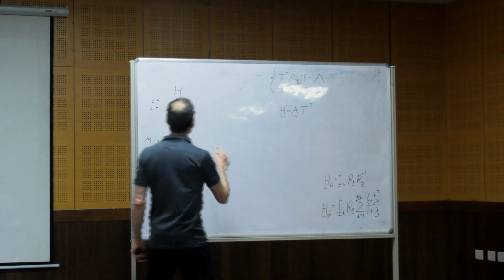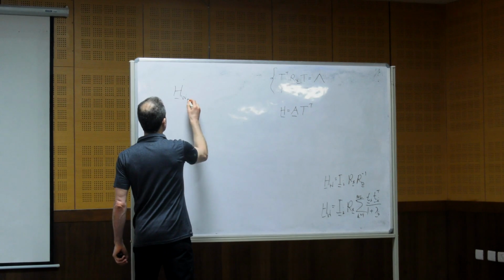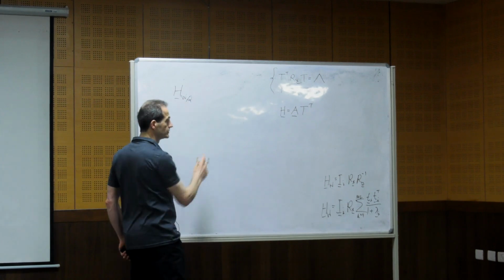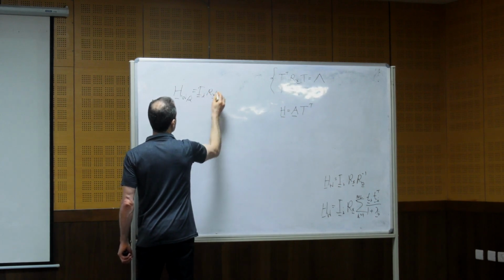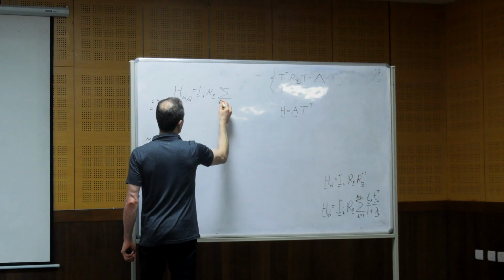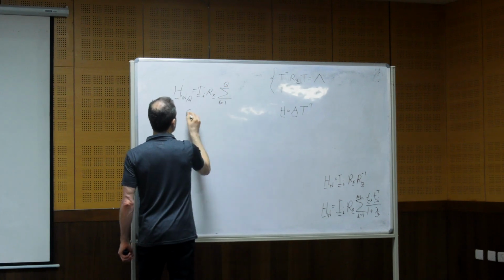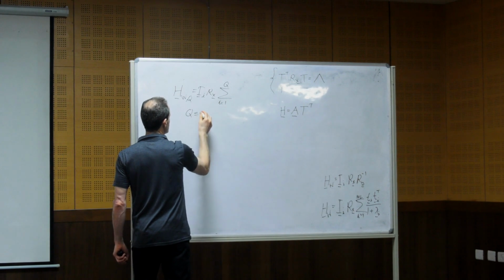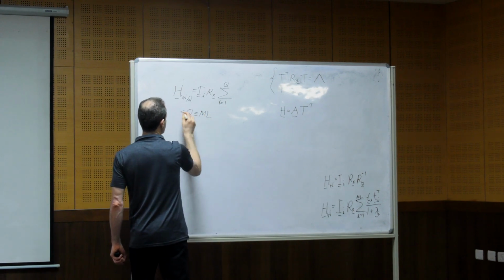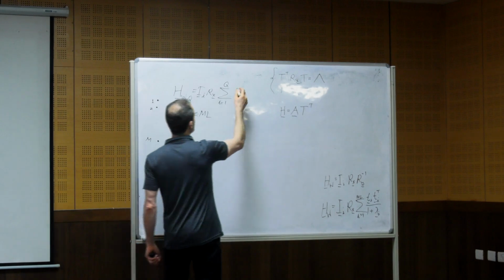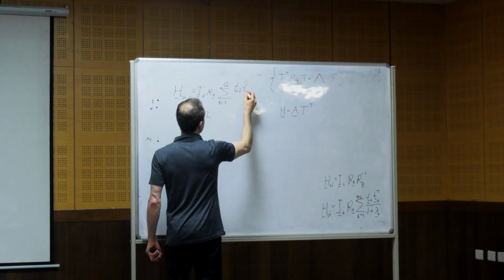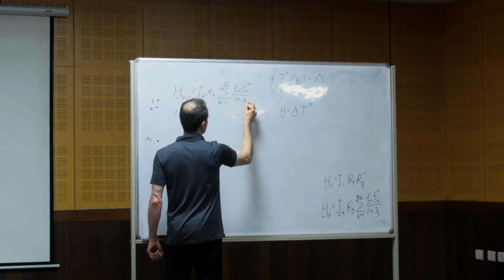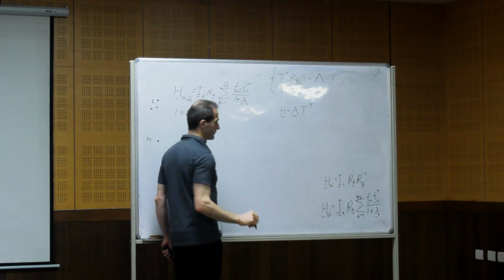But if we define another matrix with a parameter Q, a summation from i equals 1 to Q, where Q is generally smaller than ML, then we can control the trade-off between noise reduction and signal distortion, which is nice.